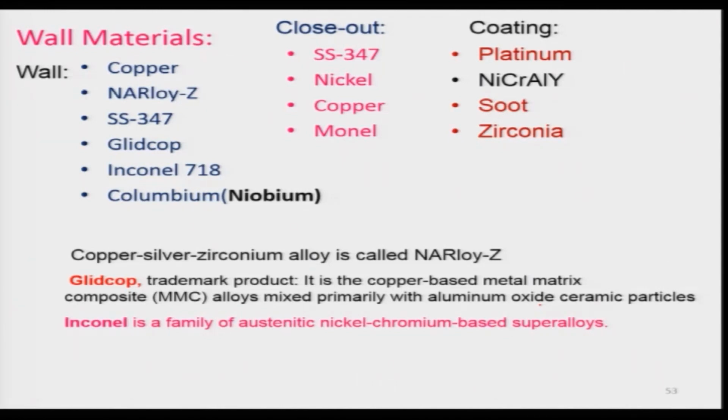NiCrAlY alloy, and even the soot particle is being coated so that heat transfer will be better, and zirconium is being used, and NiCrAlY is basically a nickel based thermal spray which is being used to coat the inner surface of the combustion chamber, so that heat transfer to the coolant can be maximized.